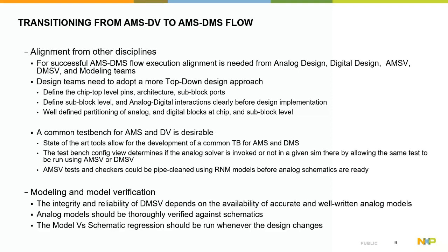So the chip architecture and the top level pins, as well as block ports, and as well as the analog to digital interactions, have to be very clearly defined. Also, a well-defined partitioning of analog and digital blocks at the chip and the sub-block level is needed. And also a desirable feature is to have a common test bench for both AMS and DMS.